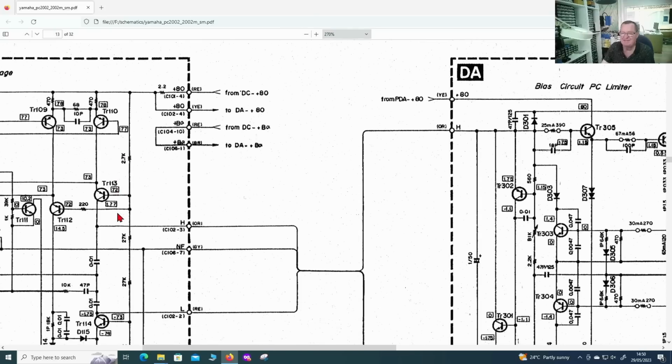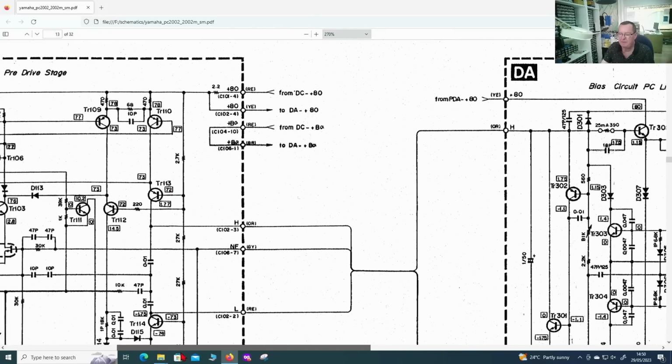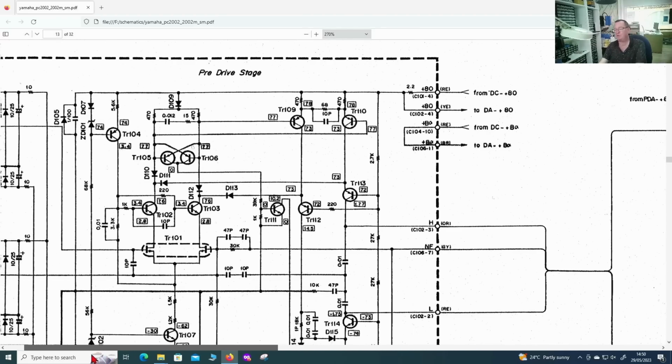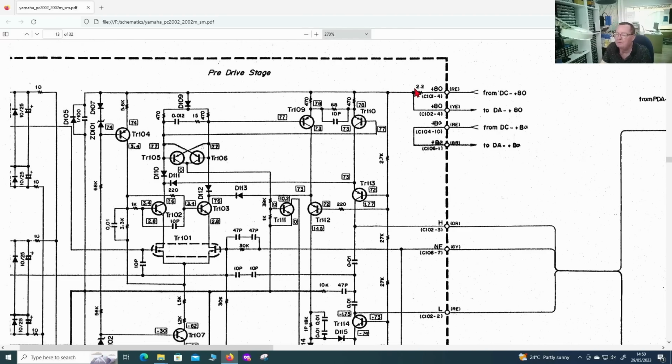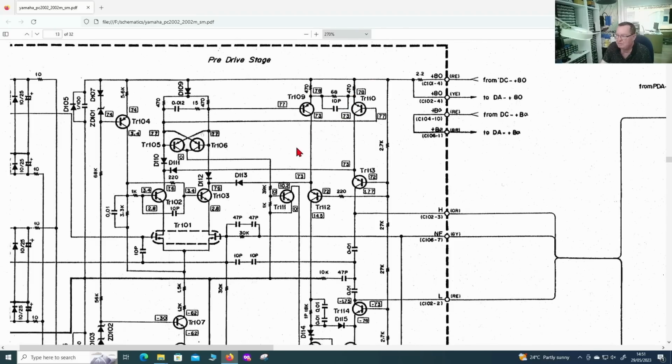But let's have a look at this side. This is where I think it might be. But remember guys, there's a lot of supposition until we prove it, okay? So in here, well, there's a 2.7k, so the problem can't be going down that way. 470, 470, 5.6. So I don't see any path down here of like 75 ohms. There's resistors in the way. Yeah, you can't be a short here because of a high value resistor. And we will see the high value resistor.